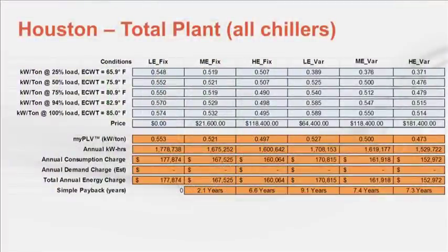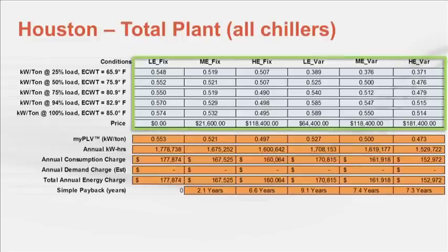To perform the analysis, the chiller performance data is entered into the spreadsheet for each of the chiller load and entering condenser water conditions specified. These are obtained from the manufacturer's selection program. Note, we have 6 columns of data to represent the 6 chillers considered. The data is input into the light blue cells with calculations performed below. The payback in years shown at the bottom.